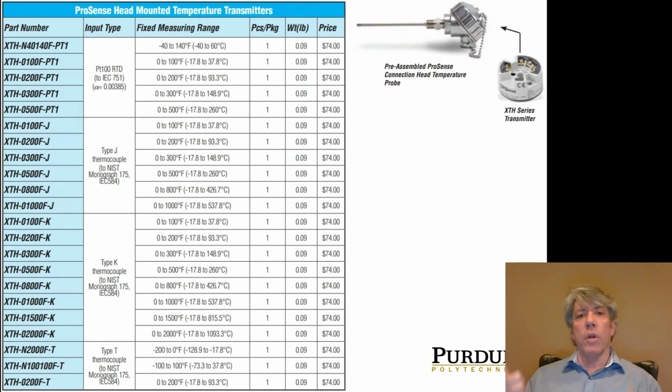And these are really good devices because, number one, they're cheap. Number two, you can get a very wide temperature range. So, for example, a Type K thermocouple is particular dissimilar metals that are well known, welded together. You can get it to measure a temperature from 0 to 2,000 degrees Fahrenheit just fine because it's metal. So if you need to measure a flame temperature, you're going to use a thermocouple to do it.